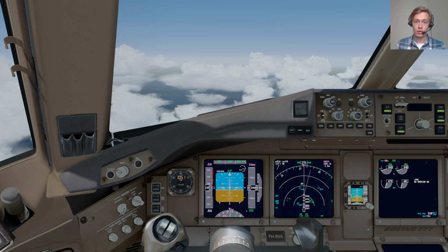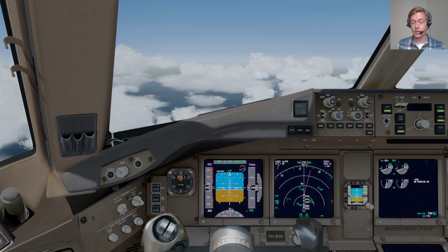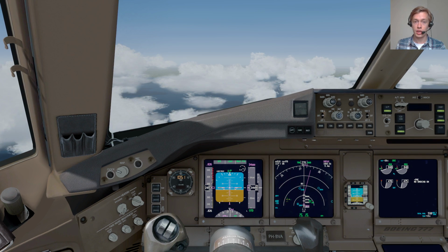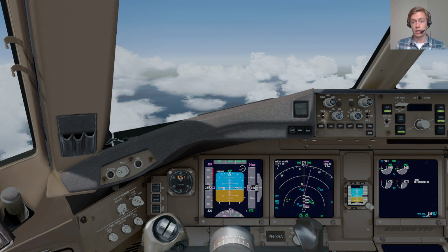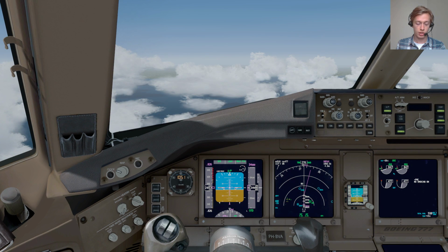You can ask the domestic controller which frequency to contact. Otherwise, if in doubt, always ask. You can always send a private message to an oceanic controller like, hey, I'm inbound this oceanic entry waypoint. Can I ask oceanic clearance at your station, at your frequency? It never hurts to ask, especially when it's not busy.